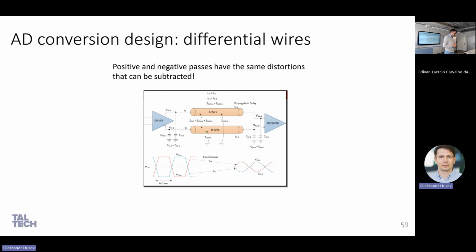But a microcontroller, in most cases, has one or two AD units but many AD channels, which means that they are not measured simultaneously. And if you apply this differential approach, you must measure them simultaneously. For that, you must use only a special differential channel. Otherwise, you will use measurements through multiplexing. And in fact, why is it needed?